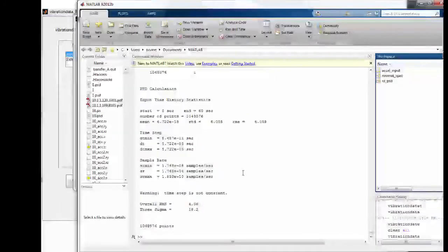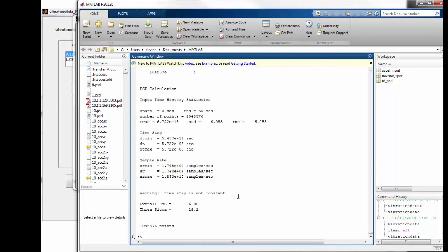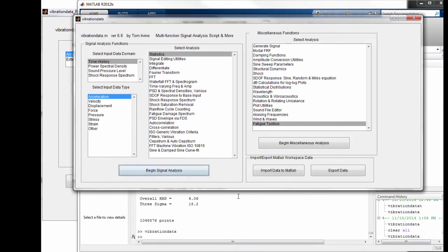So what are we going to do next? Well, let's go back to our 200 hertz natural frequency, Q equal to 10 system. Only this time we're going to do a time domain calculation. And one of the wonderful things about vibration analysis, and this is something I occasionally mention in this webinar series, is that we can do calculations in the time domain, or we can do calculations in the frequency domain, and we should get approximately the same answer. And that's a wonderful thing.